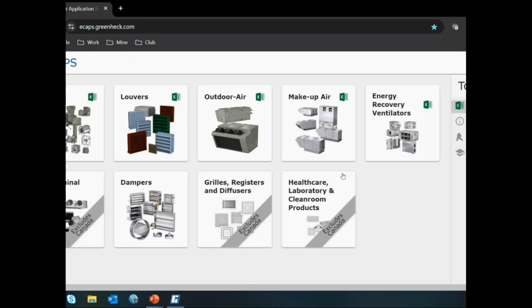Well, like most common hunting, stall, surge. You can actually create a fan that will belch. It'll build up pressure and then backflow. These things are what can happen in that area of operation, right? And that's why the manufacturer is saying just don't go in there. A lot of it has to do with the shape of the fan curve, and that shape changes if it's an axial versus a centrifugal, the size of the fan, the type of the fan. All those have effects on the shape of the fan curves.